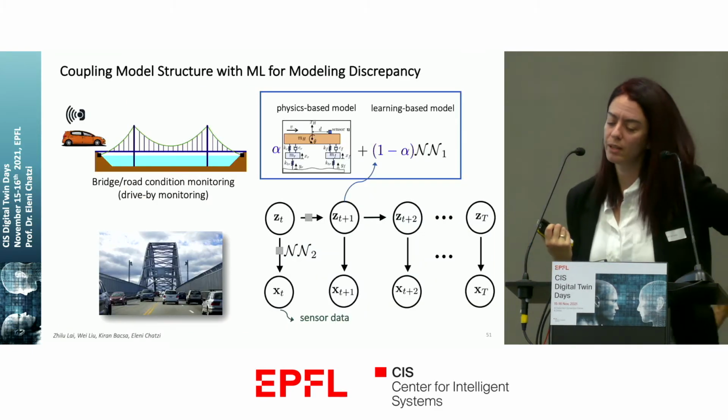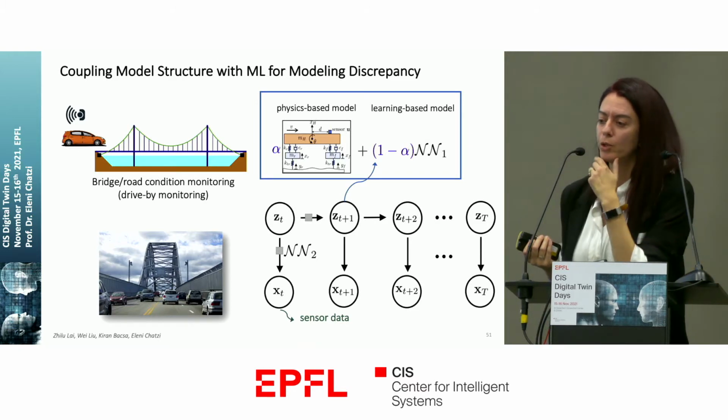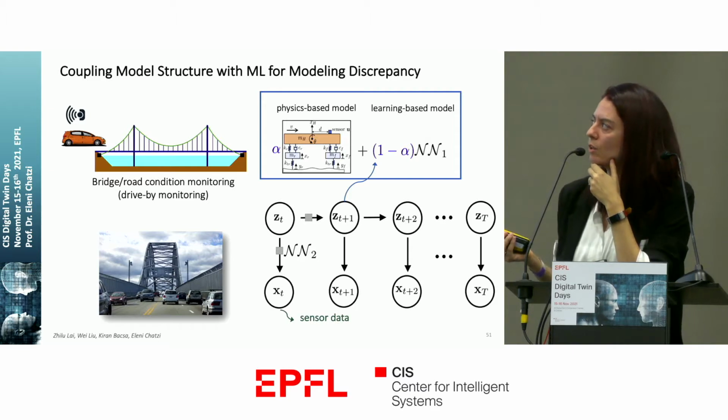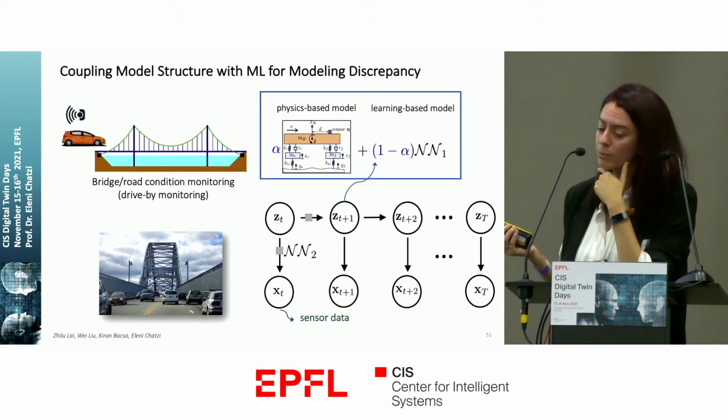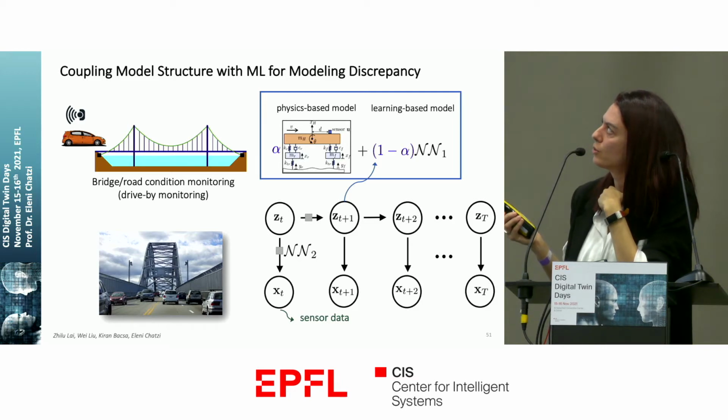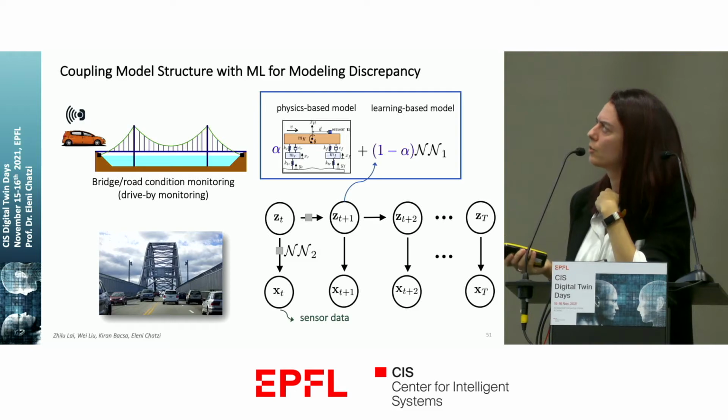We use this kind of logic for condition monitoring of roadway infrastructure, or what is often called drive-by monitoring or onboard monitoring, as you could have also heard. And here the idea is to try to use information from a vehicle that is traversing some piece of infrastructure, perhaps a road, perhaps a bridge, and from that information infer what is the response of the underlying substrate, what is the roughness maybe of the road, or what are the dynamics of the bridge.